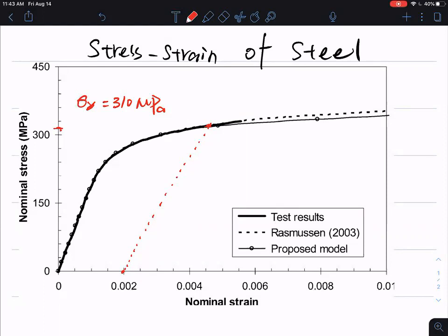For example, you want to use the same material to design a beam for the back of the table or something like that. And you know the load you apply to that beam. The beam is under tension stress, tension force. And you can refer to this diagram and find out what deformation you get under that stress without holding the experiment.